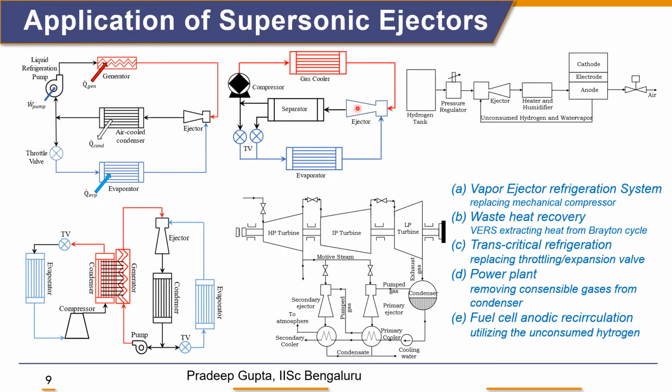So just to improve the efficiency, we are using the ejector as an expansion device where the high pressure gas expands to intermediate pressure by mixing with the evaporator fluid, and also the evaporator fluid is slightly pressurized, which requires less work from the compressor. After that, the liquid and vapor parts are separated in the separator.